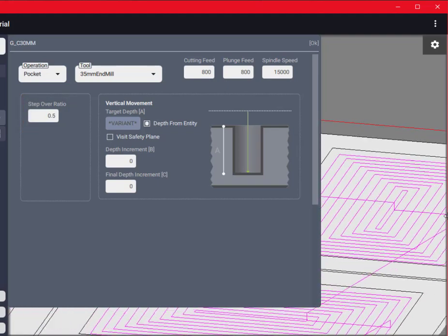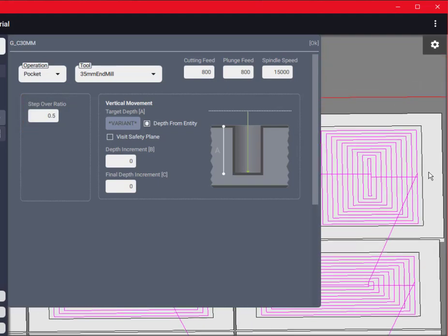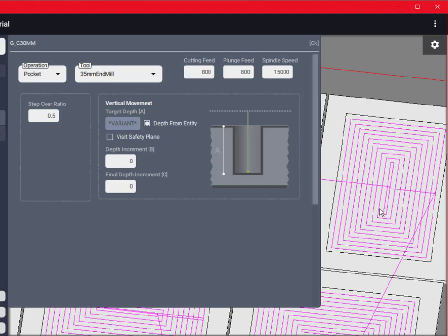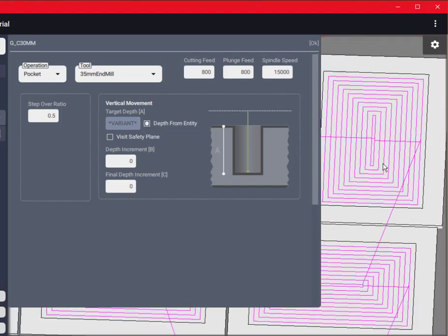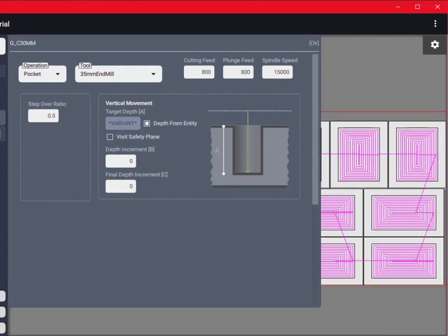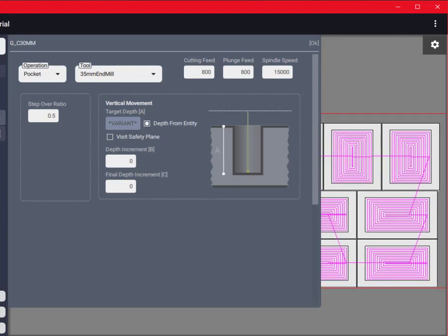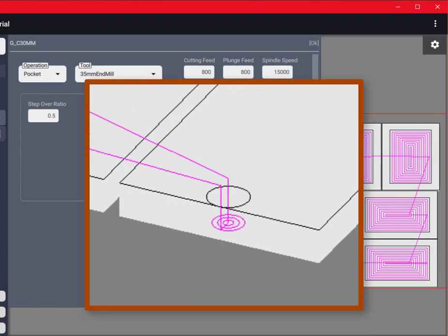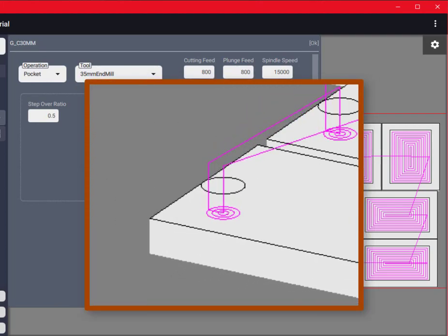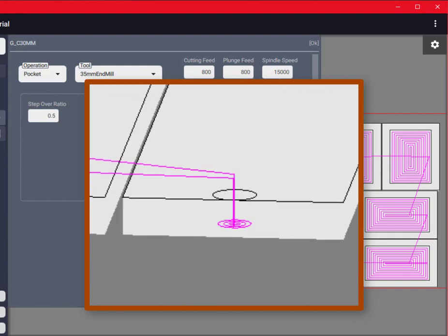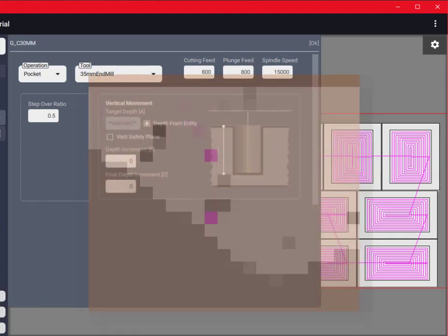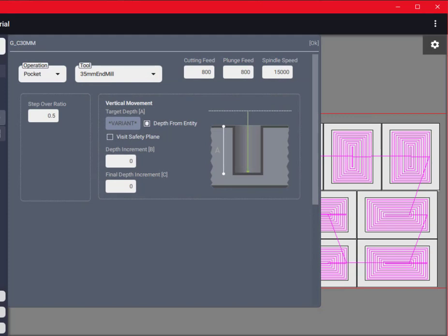We can use this operation for other purposes as well. As an example, let's assume we have a large hole for which we do not have a tool, but many other tools with smaller diameters. In this case, the options are either to wait for the purchase of the tool with the right diameter or to use a smaller tool instead. Using a smaller tool and pocket operation would make the manufacturing process a bit longer for these geometric features, of course, but this flexibility would pay off considering individual projects.